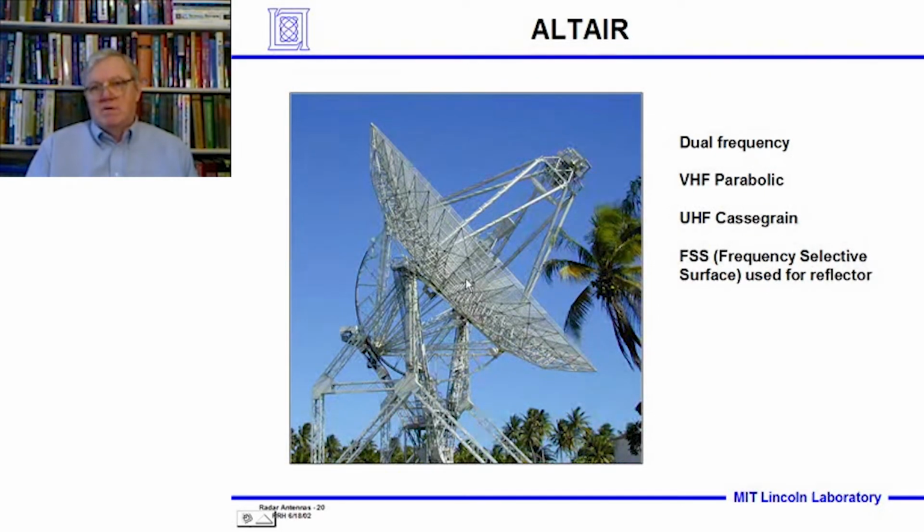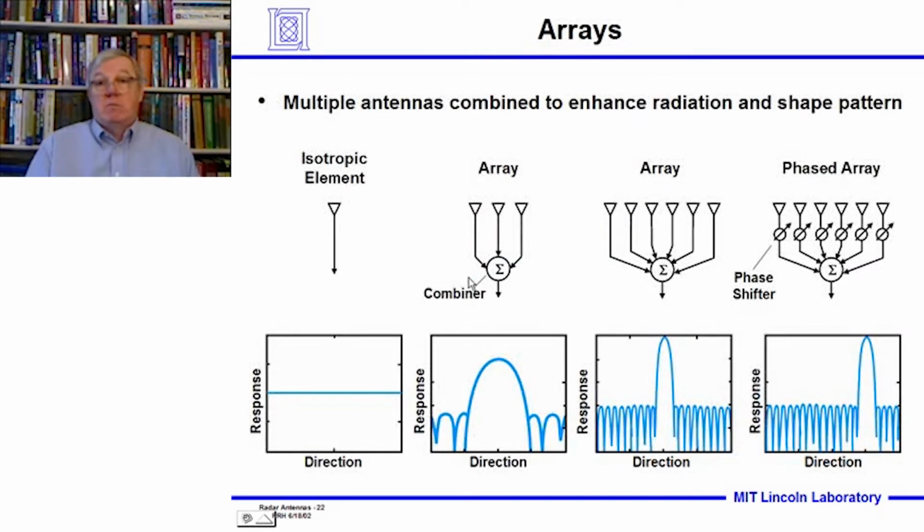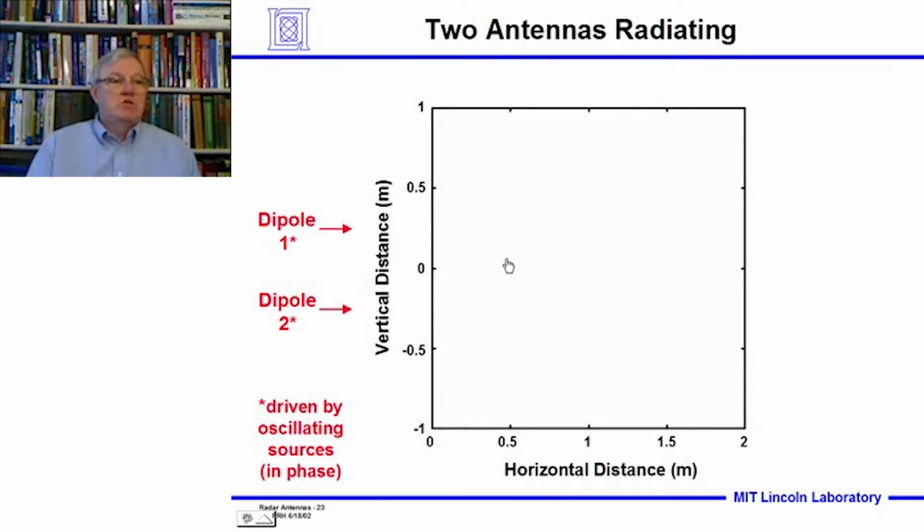Enormous job. But if I could have this antenna face be a whole raft of elements, a whole face of elements, and I could just change the phases in microseconds, that beam could be pointing over in another direction microseconds later. And that could allow me to flit back and forth the beam. Okay, that's a neat idea, and we're able to do that with today's technology, and that's called a phased array antenna.